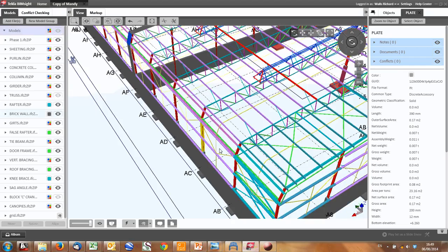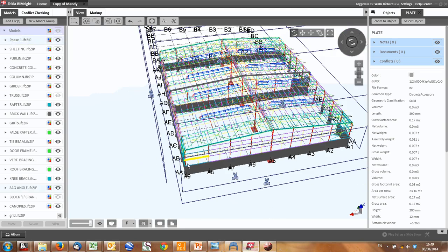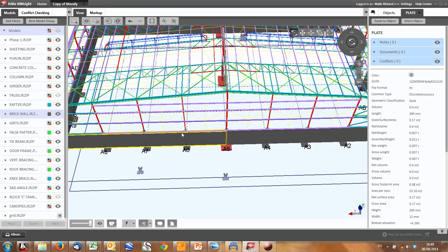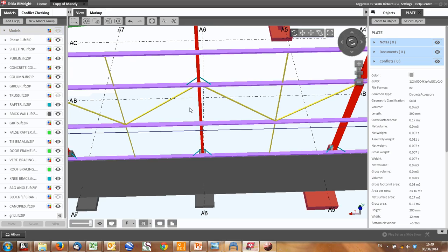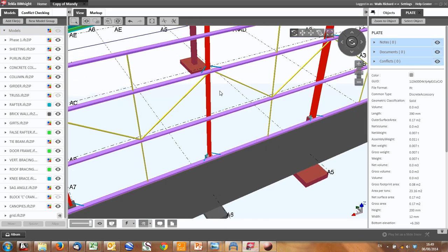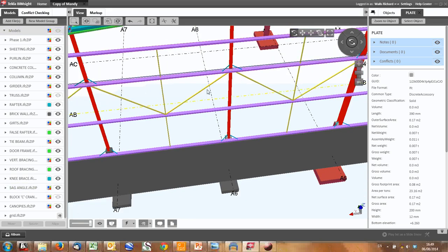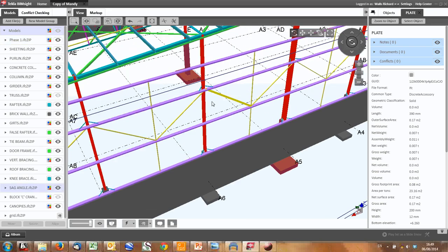So if we look at our model, wind load comes across the structure. But what happens if the wind blows from the other side? How are those loads taken? So you can imagine, I can apply a little load here to the sheeting. How are those loads carried? Same question. So obviously, this goes up the sheeting and down the sheeting to our girts, from the girts to the column. The column then, how do we design this column?